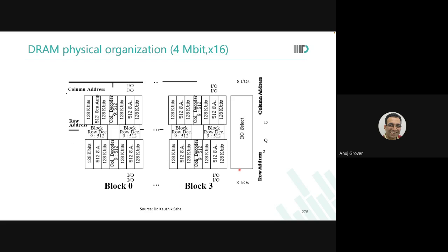In DRAMs, one page has only one bit of each word. So if a high energy particle comes, it will corrupt bit number 27 for 20 words. Okay, no problem. Only bit number 27 is corrupted. So when you now need to read from this DRAM, you can very easily correct the error.